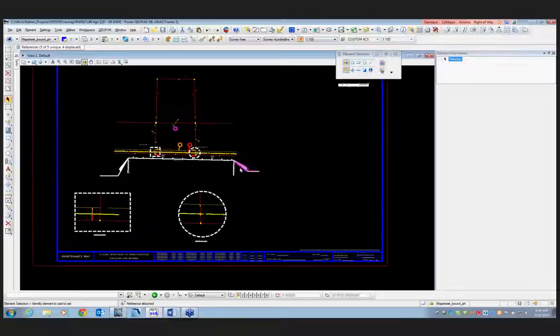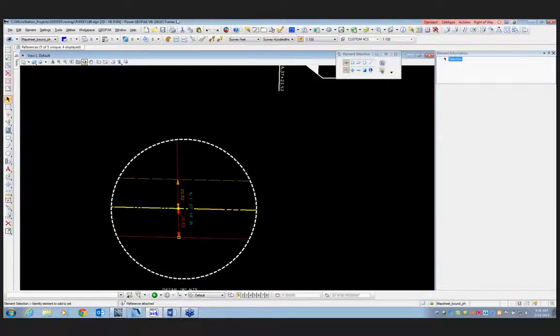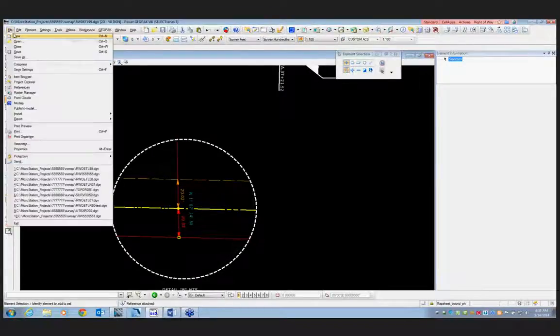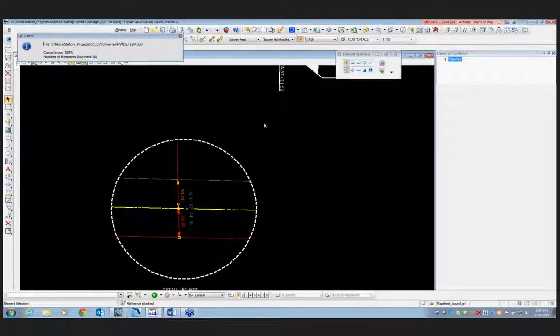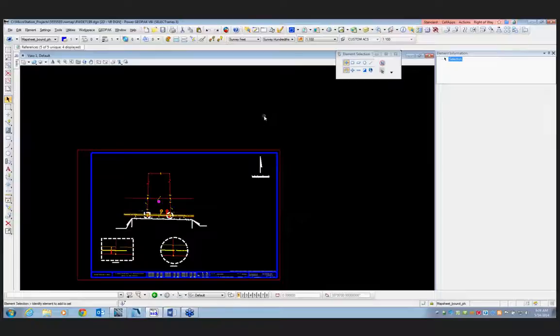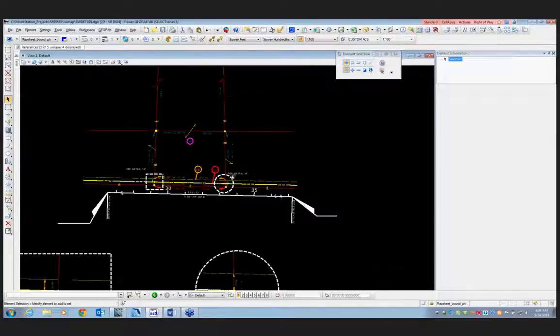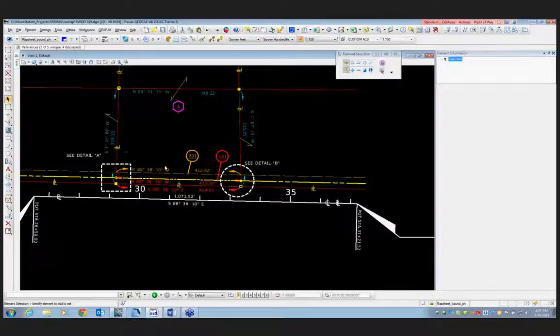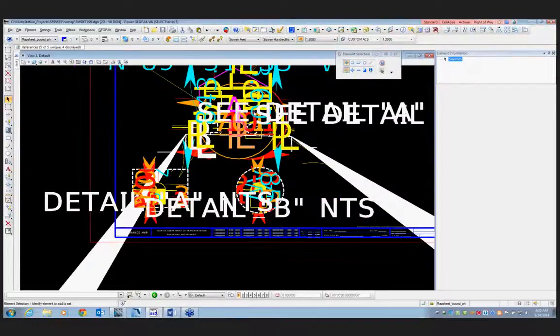I want to give you a little sample of how I set these details, because these details are reference files. They're not clips. They are actually directly from the master right-of-way file. So what you want to do is, if you go into the master right-of-way file and you have an area you want to show in a detail, go into that master file. I'll show this general area right in here, and just to show you how the references work, I'm going to set this to something crazy like 2000.